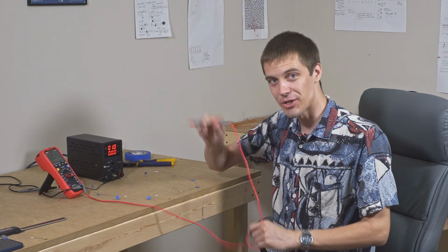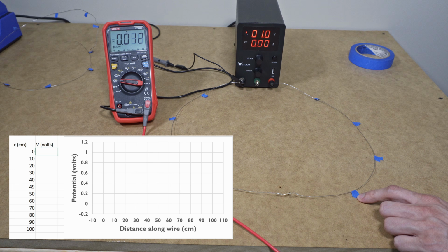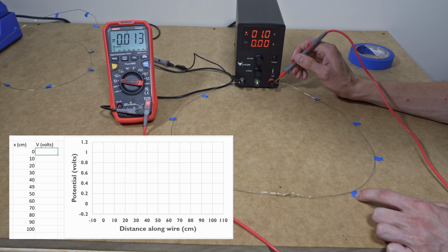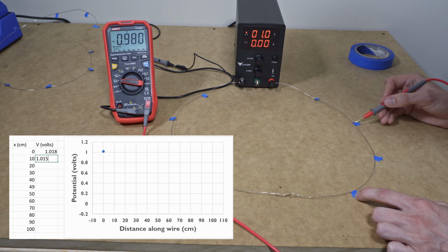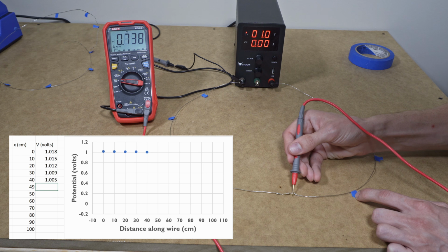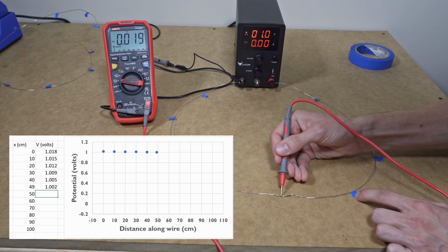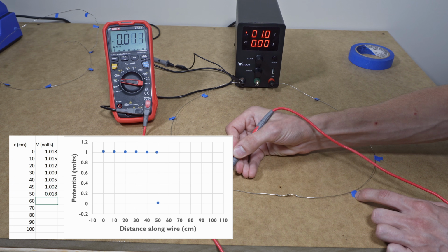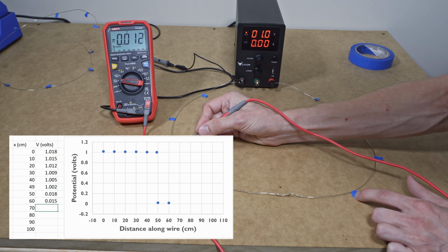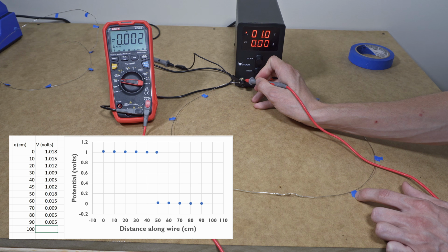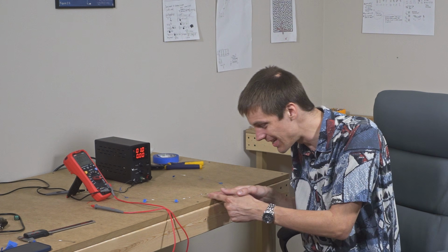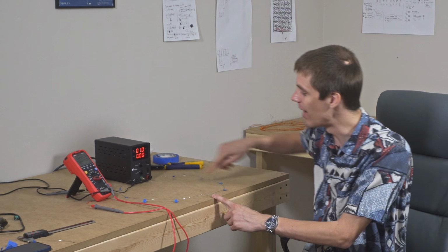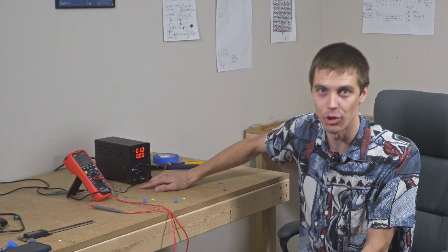But when we do the same experiment and we look at the voltage around the loop, we see something pretty interesting. Over here by the positive side of the power supply, we still see a volt. But as we move around, that's still a volt, that's still a volt, that's still a volt. And then on the other side of the resistor, we see just about 0 volts, all the way back to the power supply. So we have turned this smooth gradient into a step where all of our voltage is being dropped in this one particular spot at this component, rather than smoothly declining as we go around the loop of wire.